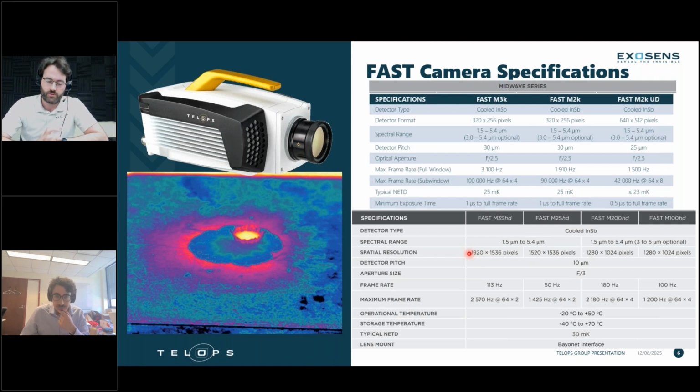So nice, crisp, and high spatial resolution image that gives a lot of information for your image. It's important to remember that with the image that you get for these cameras, every single pixel has a radiometrically calibrated data point in it. So every pixel has a specific temperature point or radiance or irradiance, depending on what kind of data you want to use.